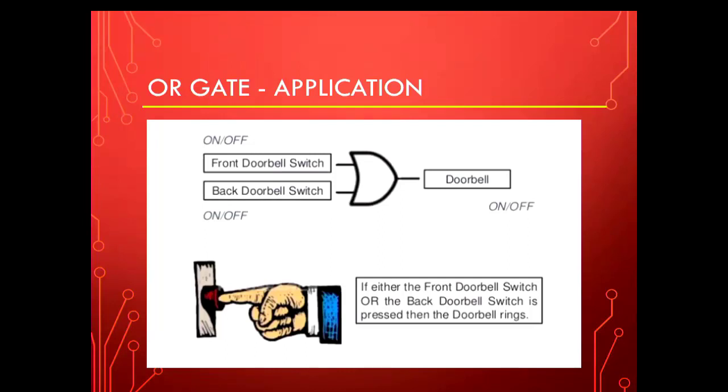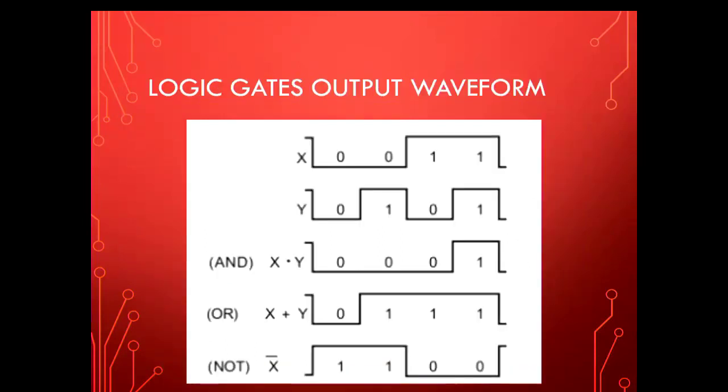We saw one application earlier for an AND gate and an OR gate, the light bulb, also. This is what we refer to as a timing waveform, and we will be doing a lot of it. You have x and y, and on the x-axis you have time, which could be in nanoseconds or milliseconds. When x is 0 and y is 0, the AND gate creates 0 because both inputs are low.